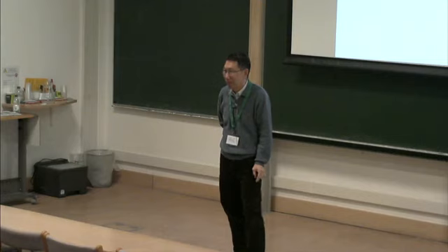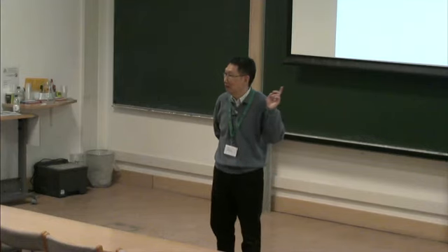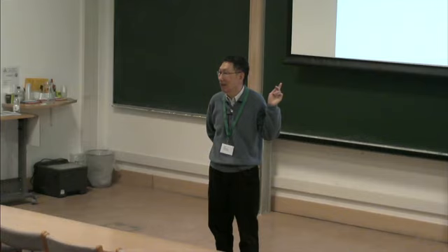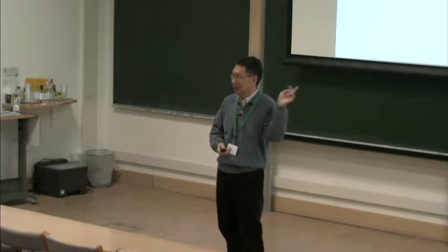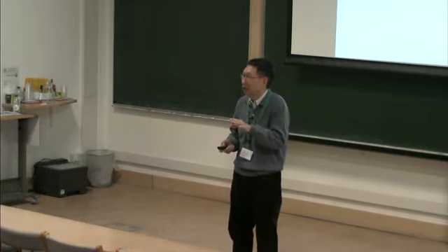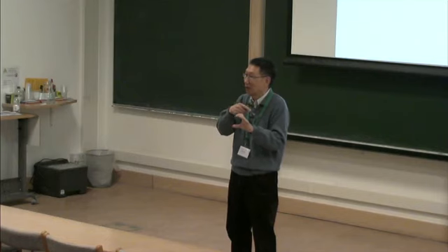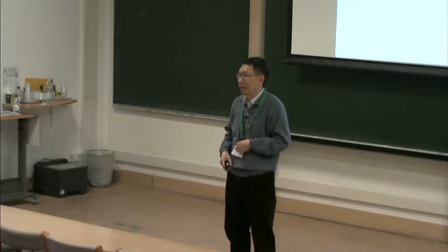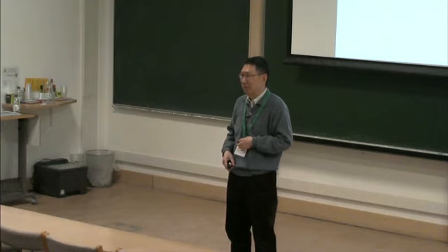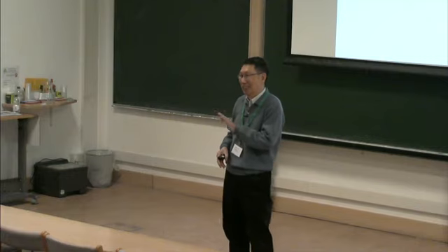Jukka, neither you nor, earlier this morning, Steve, mentioned anything about thermal cracks. Some effect is there. I just didn't go into the detail. We can calculate the thickness, and as I showed, we can also calculate the deterioration of the cover with an Ashton type of approach. Another question is that you both showed the same photo of a longitudinal crack in the middle. It very much looks like there was thermal compression or something like that. It doesn't look just like bending. It looks like there has been some compression.